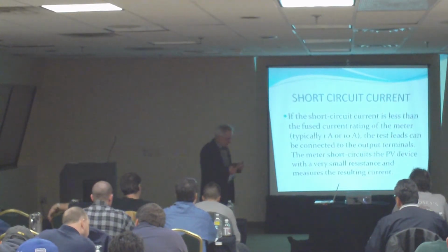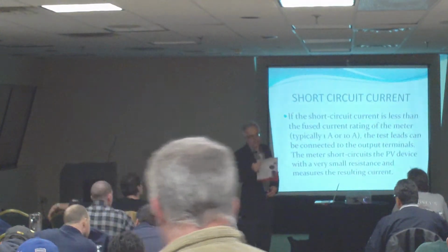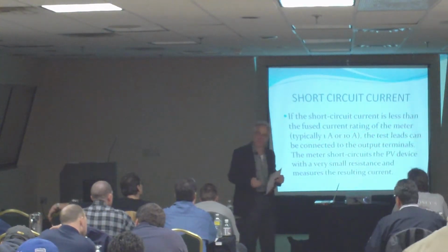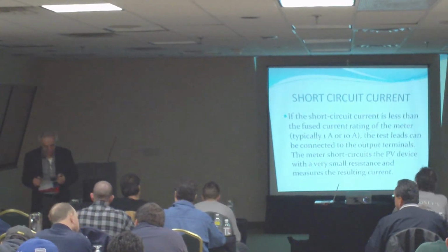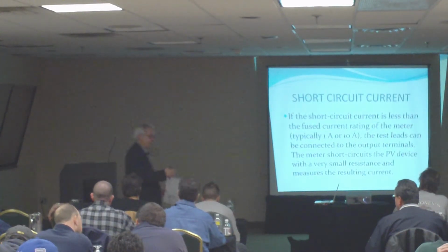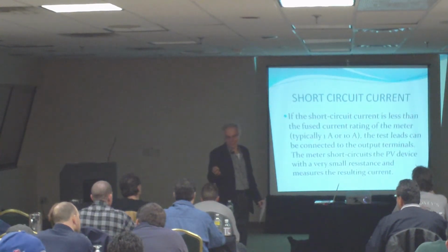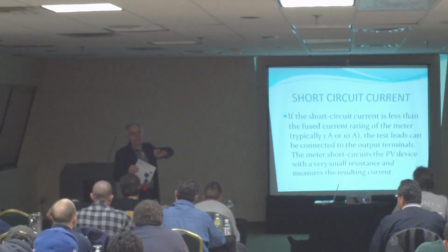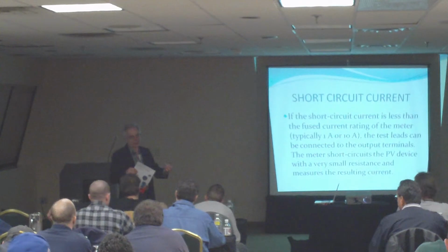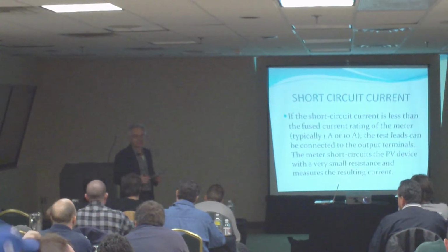And then something called warranted minimum power, okay? So in this particular case, they have that this is a 185 watts module. And then they have here a warranted minimum Pmax of 179.5 watts. What does that mean? I guess what happened is 185 watts is under standard laboratory conditions. Okay. Perfect conditions in the lab. 179, 180 watts is under what conditions?